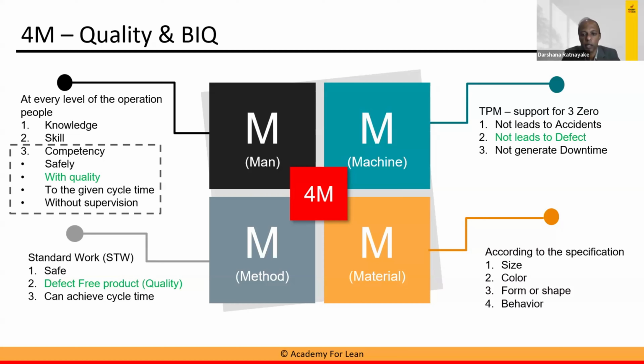And the last M is material. There we discuss how material has a link to quality and what we can do to eliminate material leading to defects, and what ideas we can get simply from the normal procedure where 10% inspection was there. In the cutting they check, while you go through the layering part, and after that there are many checking points before coming to the sewing line. In the sewing line there are some inline quality and endline quality. At the end of the line there are measurement people, checking people. There are some areas where we have checking points to measure the material also.